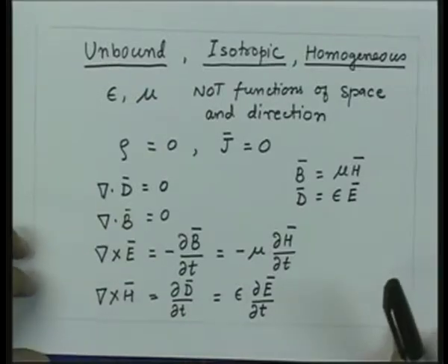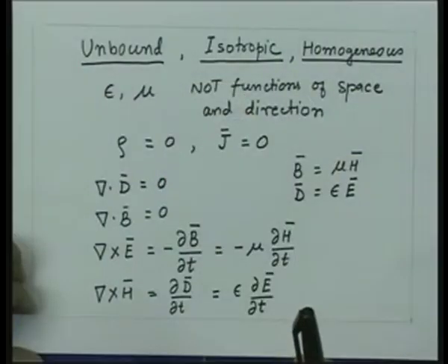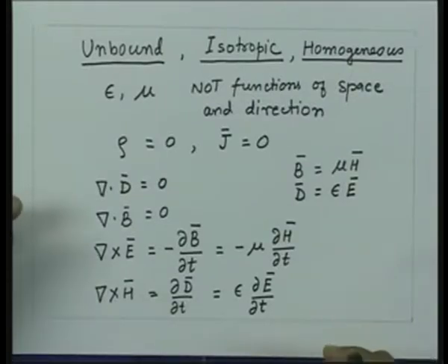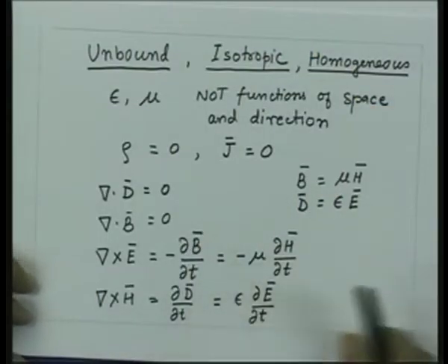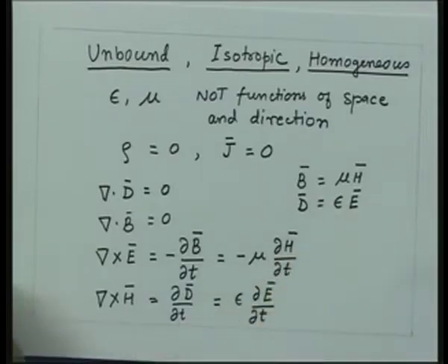In electrical engineering, invariably we solve the problems for periodic signals, and a periodic signal can be decomposed into its Fourier series. So essentially, if you find out the behavior of a system for a sinusoidal signal, we can always find the response of the system for any periodic signal. So let us assume, without losing generality, that we investigate the problem here for time harmonic fields. That means the electric and magnetic fields both are sinusoidal functions of time.